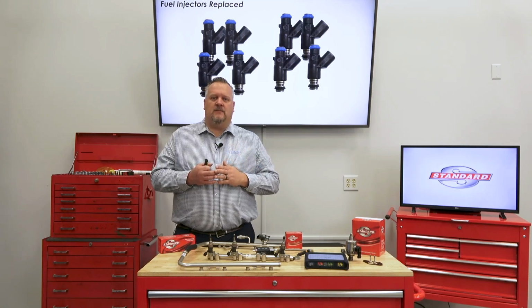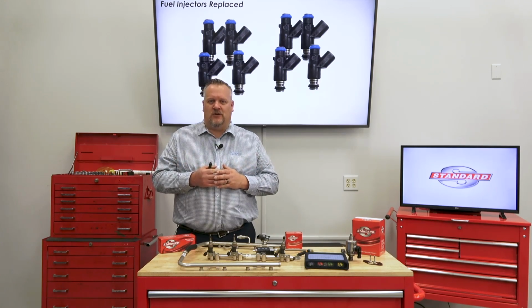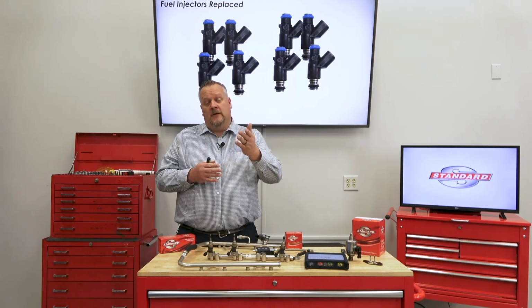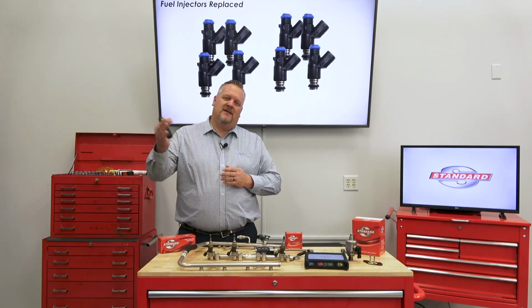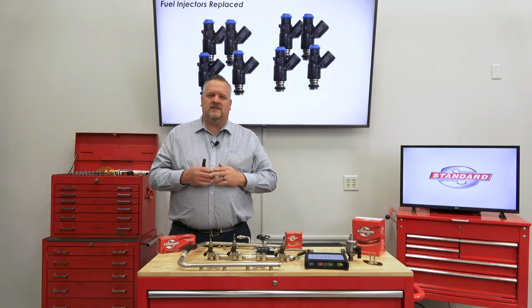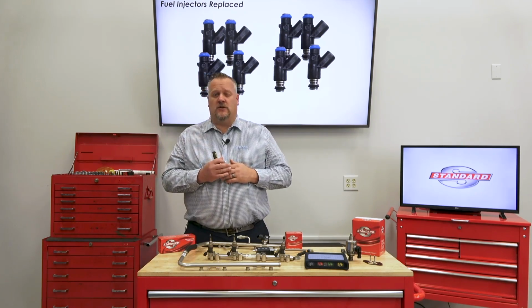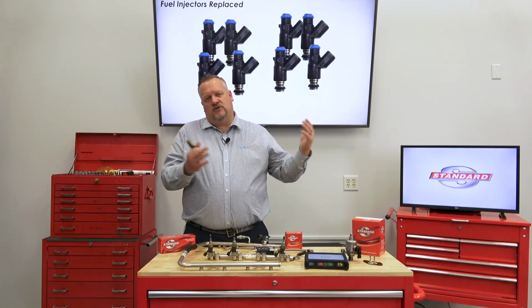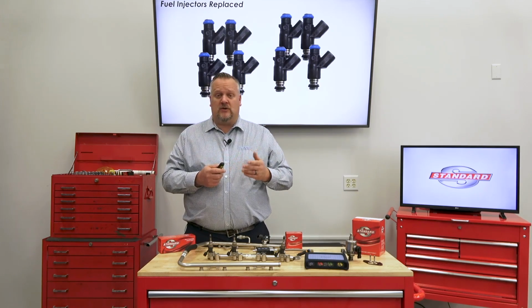I know sometimes it's hard to talk the customer into doing that. And in some states, some of those might be frowned upon unless the customer makes a request, as we've seen here. And so in this case, 4 injectors were replaced. The fuel system was actually flushed and the filter was replaced ahead of time also, which are great pieces to make sure that we're not contaminating the new injectors here.